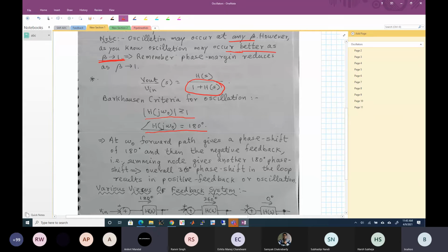No, not like that. See, when you build an oscillator, you are building it to oscillate at a particular frequency. You can design oscillators in different ways. One of the ways is you can purposefully put positive feedback. In another case, you can put negative feedback, and at one particular frequency, that negative feedback becomes positive feedback. That means the Barkhausen criterion is getting satisfied at that frequency.